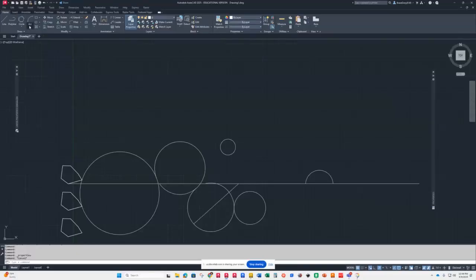we've got our circles. The next thing are arcs. I'll just be honest with you, the 3-point arc is probably one of the few ones I'll use occasionally. You pick 3 points that you need. There you go. Now, if you hit A for arc, it defaults to a 3-point arc. And let's say you said tangent, T-A-N, enter. And then I want it T-A-N, enter. So you can type in your object snaps. And then let me see if I can make it tangent to this guy. T-A-N, enter, and I'm going to pick that guy right there.